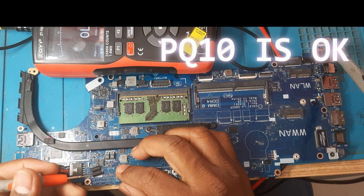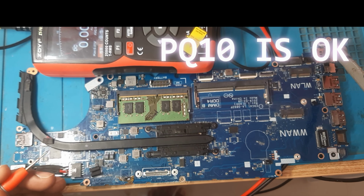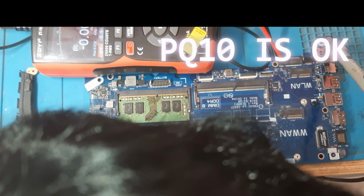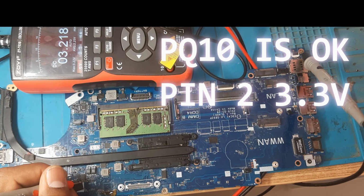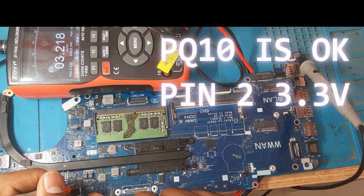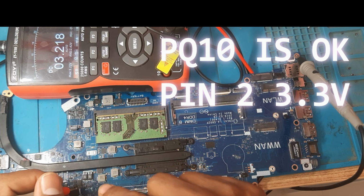Okay, it's a voltage. See, pin number 2 receives 3.3 volts. Okay, it means if pin number 2 is present, then pin number 3 should also have voltage and the remaining should all be ground.